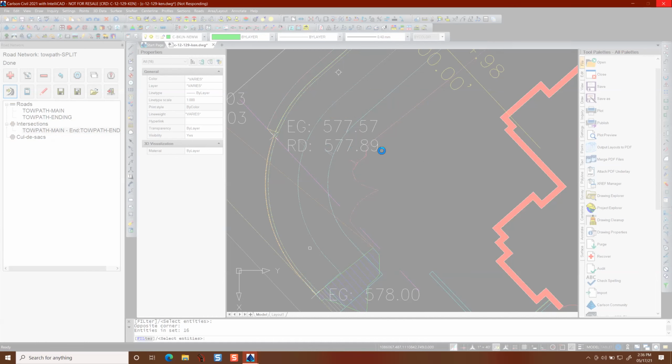The only way I could get it to stop at our 250 feet was to tell it to not do the intersections, because that intersection part is what overrides that length. It would go up to your station limits, and then find the intersections and go to whichever is the furthest intersection, which in our case was at the end of the road. So it wound up doing the whole road. We turned the intersection processing off and it finds it just fine.